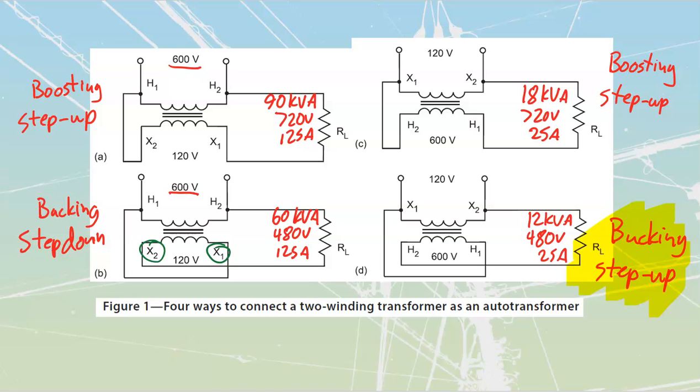Bucking and boosting does not mean step up, nor does it mean step down. Over here, I see that I have got a bucking type of configuration, but it is still a step-up transformer that we have. Over here, I see that I've got a boosting, and it is a step up. Over here, I see I've got a boosting, and it is a step up. Over here, I see that I've got a bucking, and it is a step down. They are not tied together. That one can only ever be the other. So just don't use those terms buck and boost unless you actually are comfortable in what those things mean.